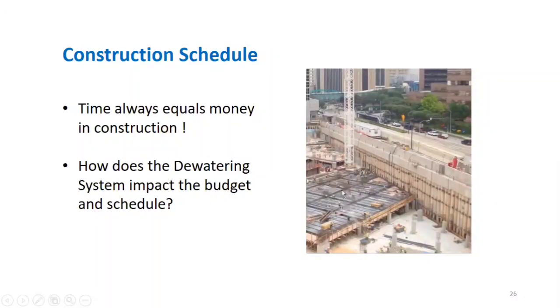In these situations, the method you are using for dewatering will again be affected by what type of construction activities you have. You can see in this typical figure that within the basement there are dewatering systems installed. Maybe they're not clear, but you can see the pipes from here, the secant piles as well, the retaining system, and the existing structures nearby. So this is a very sensitive dewatering system project.